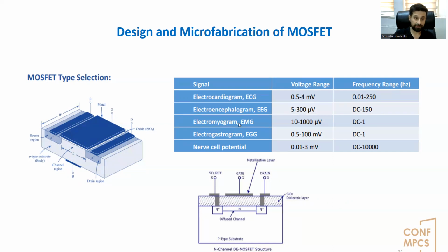The electrode presented here requires a MOSFET to convert biopotentials to an amplified current form. The carbon nanotubes capturing the biosignals from the skin surface are connected to the gate of the MOSFET. Thus, the threshold of the MOSFET has to be low enough to be in on state for all the biopotential range, or the MOSFET has to operate in the saturation region continuously.